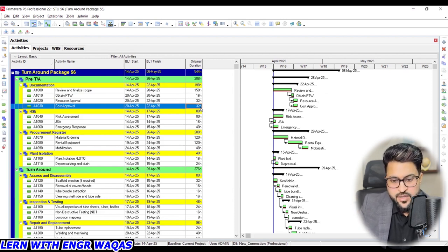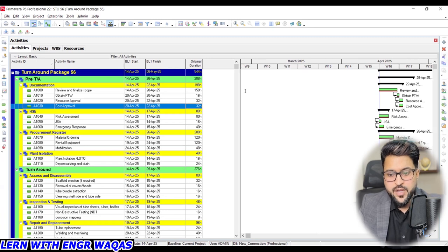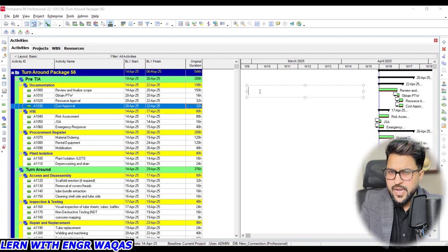You understand? And usually benchmarking the previous data is going to play a very important role, and you can make a productivity goal as well, such as dealing with specific gate valve maintenance. So the benchmarking is going to help you. For that gate valve, opening the nuts and bolts will require maybe 30 minutes, or say 1 hour.